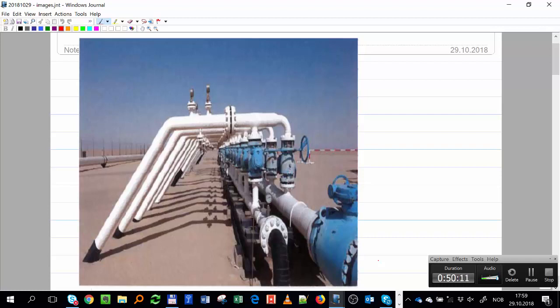Where do we have the isolation valves or the routing valves? Okay, from here goes well one, right? Here this goes to the test separator, and that goes to separator A, or the production separator. Here it comes from the well. If I want to produce to test, open this one, close this one. If I want to produce to production, open this one, close this one. So that's a production pipe. I think this is a field in Libya.